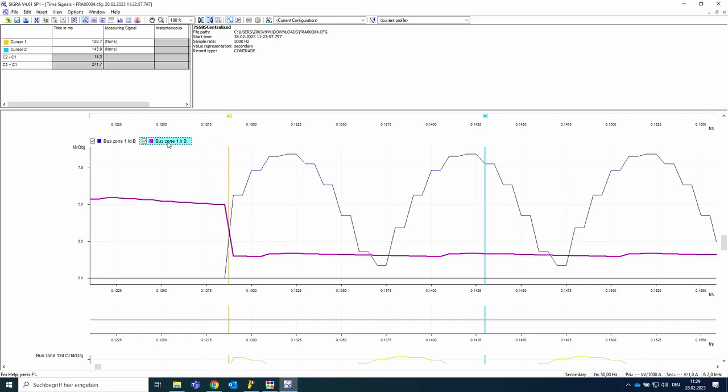And once again, that's very important. With unbalancing, you will never have a 1 out of 1 trip. As with unbalancing, you will have no jump of the stabilization current, because the jump of the stabilization current will start typically at the beginning when the circuit breaker failure protection picks up at all, but not in our case, the delay time T2 130 milliseconds later.